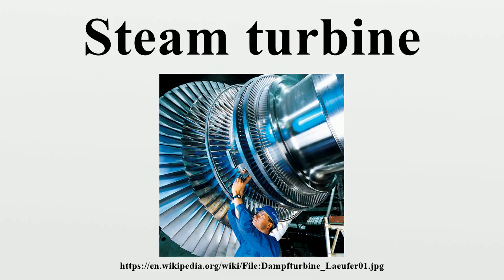Extracting type turbines are common in all applications. In an extracting type turbine, steam is released from various stages of the turbine, and used for industrial process needs or sent to boiler feed water heaters to improve overall cycle efficiency. Extraction flows may be controlled with a valve, or left uncontrolled. Induction turbines introduce low-pressure steam at an intermediate stage to produce additional power.